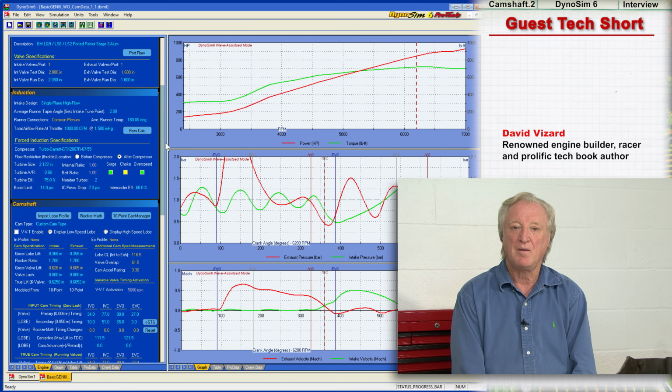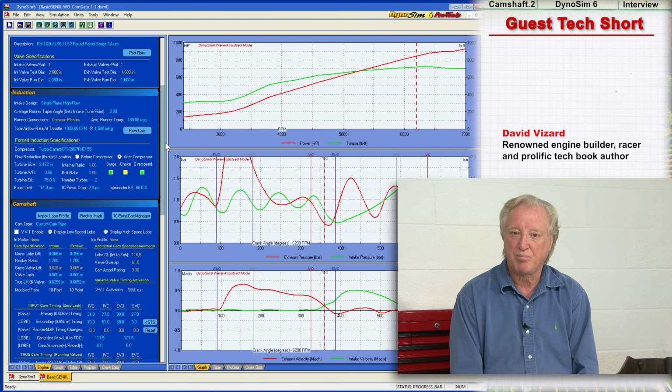Is this going to cost power? There is a misconception that no matter what you do, a silencer or muffler is going to detract from the capability of the exhaust. This need not be so. How is this doable? Well, the first thing is you have to look at the exhaust system as 2 fundamentally separate things. There's the exhaust manifold that creates the pressure waves that extract the combustion chamber charge and induce the fresh intake charge. Then there is the part of the system which must suppress noise.